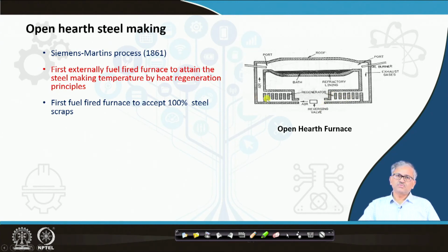In the next cycle, now that it is already heated up, the air goes through it. The air gets preheated, and then the preheated air burns the oil, and the exit gas comes and again hits the brickworks. In the next cycle, the air goes the other way through the heated brickwork, it is preheated, it is burned at the oil burner, and the exit gas comes and again preheats the other brickwork and then comes out. So this runs in 2 cycles.